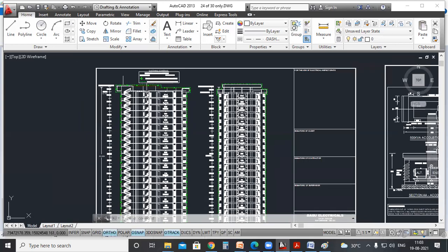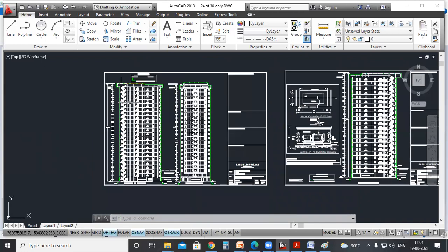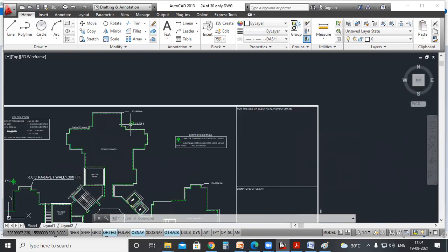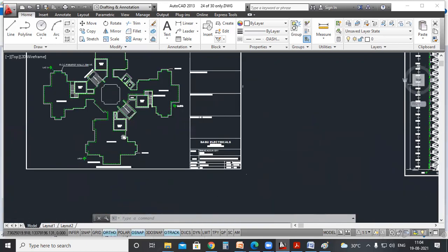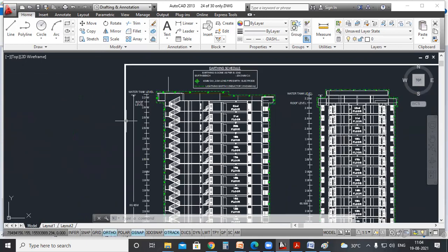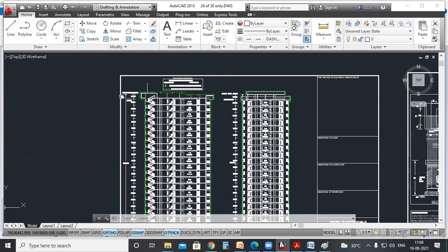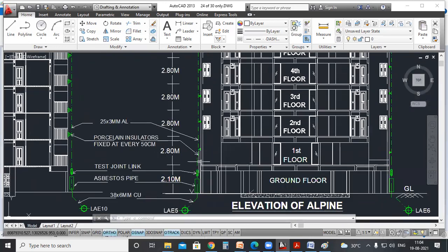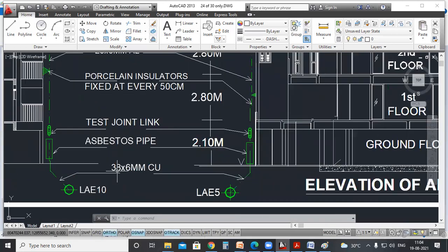So these down conductors have to be brought down. How many down conductors do you need? It is based on the total area. Here you have four, so that is why we have provided four at each tower. One here, two, three, four. These are brought down using 28.5 into 3 mm copper or GI strips. After reaching the test link, the size changes to 38 into 6 mm. Minimum it should be 32 into 6 mm.